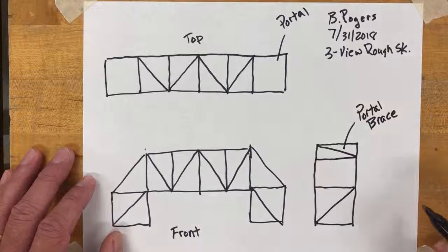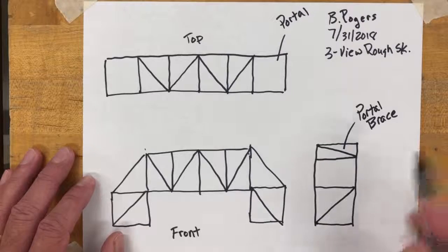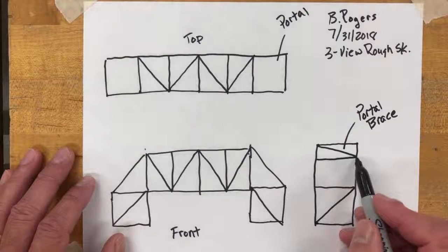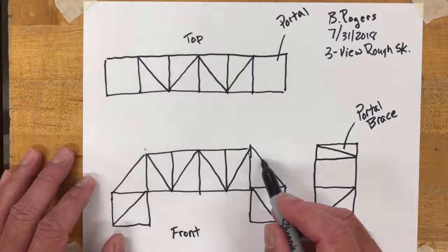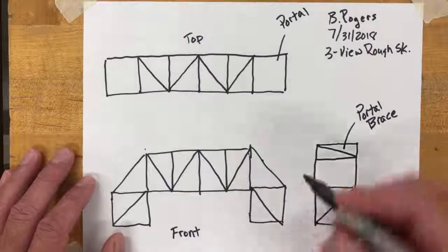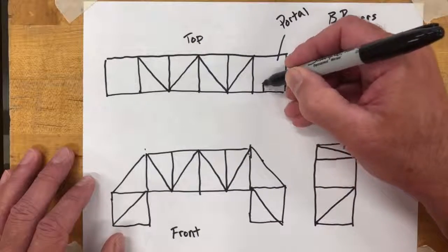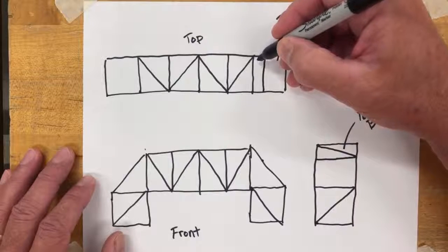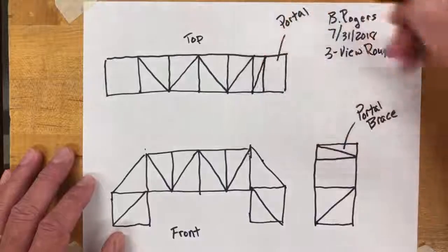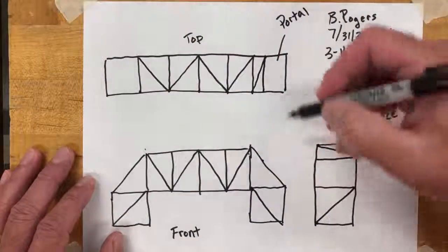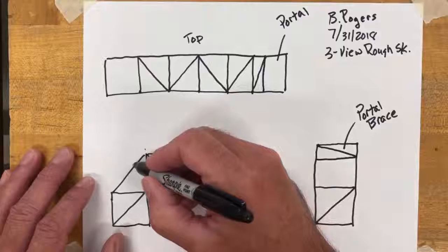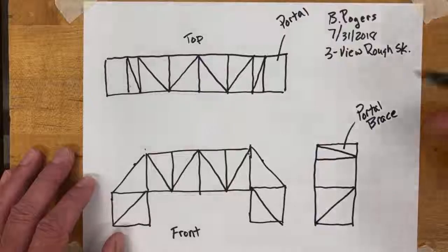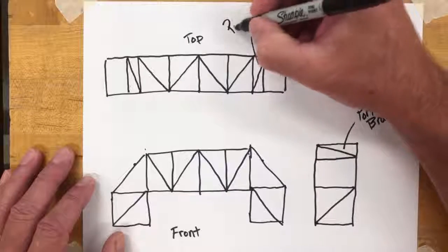All right, so that's pretty well done. Got a few details to hammer out. Like for example, in the top view, we still need to draw the portal brace. So watch how I do this. I go ahead and project over here. This is just estimating a point right about here. And in line with it, I'm going to draw a little portal brace here in the top view. And let's see, I think it's going to slant up that way. And we need one on the other side too. So once again, I kind of project through the structure here and then up. And I'm going to put a portal brace there. And so we can label it here in the top view as well, portal brace.